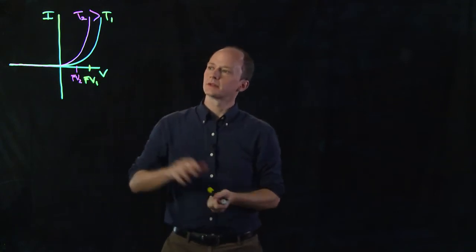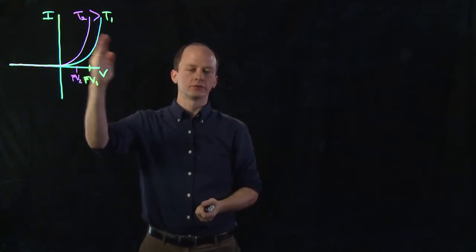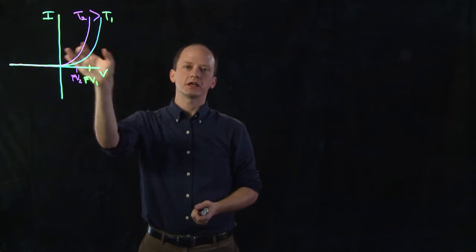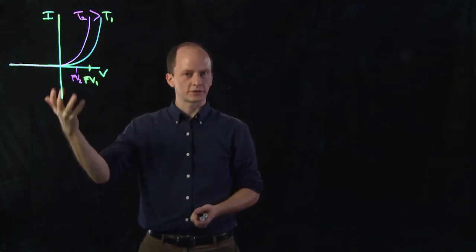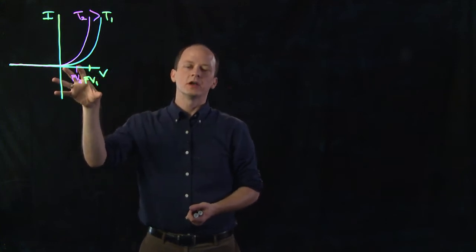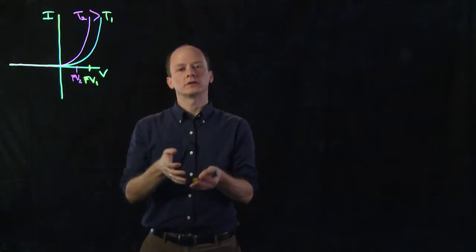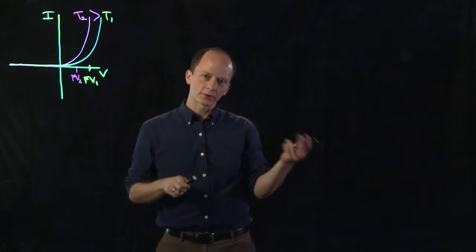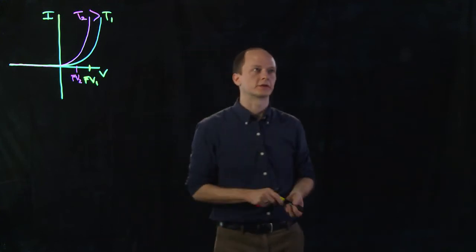So we can use this temperature sensitivity of the forward voltage of diodes to detect changes of temperature. We can actually use it to measure temperature. What we're going to do in your design challenge is use this property to control the toaster you made last week. Okay? So let's work through the basics of that circuit at least.